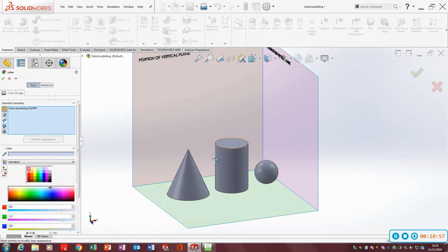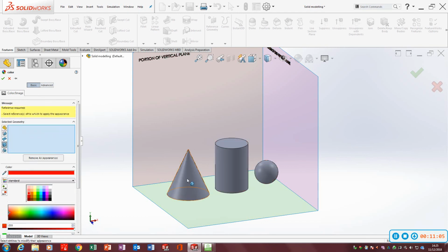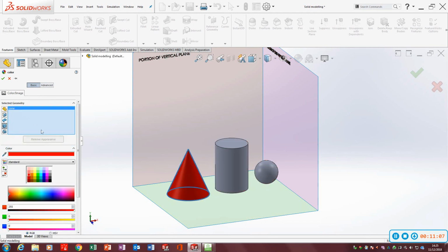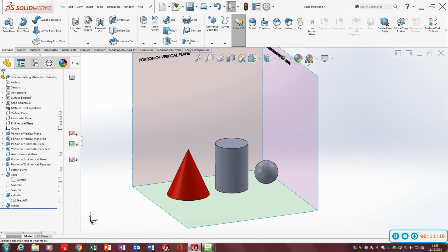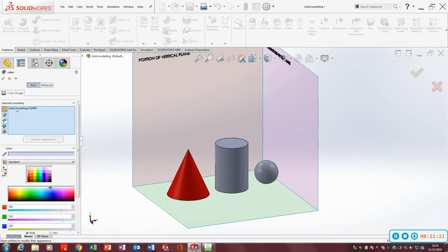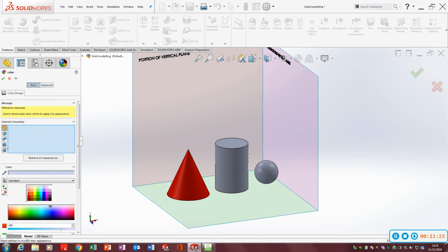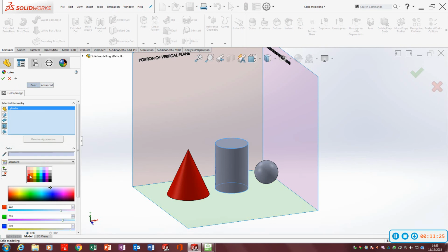And now I'm going to teach you how to change the color. So appearance, okay, and under bodies, what you can do is change the colors there. You have to right click, clear selection first. And it's disastrous the way you can't do them all in one go with different colors. I would love that, but you can't. Right, so click OK, appearance, clear selection, bodies, green,